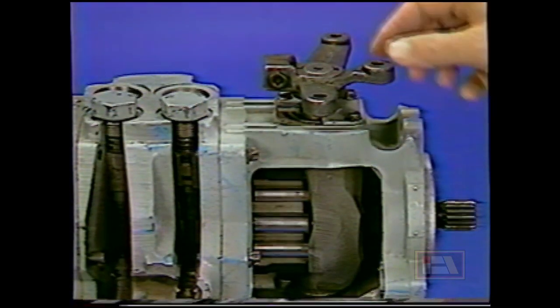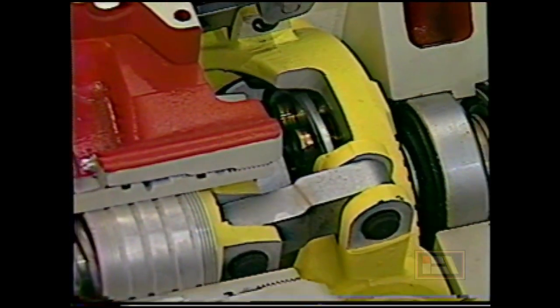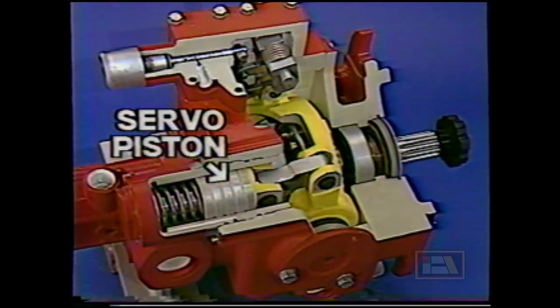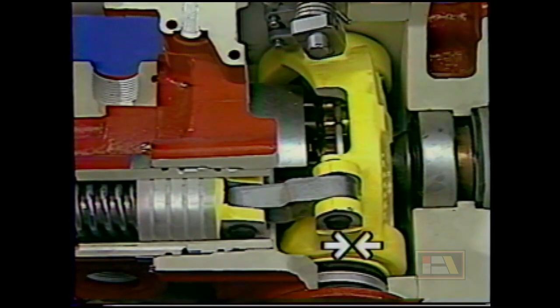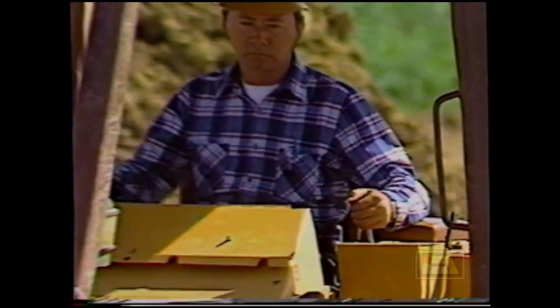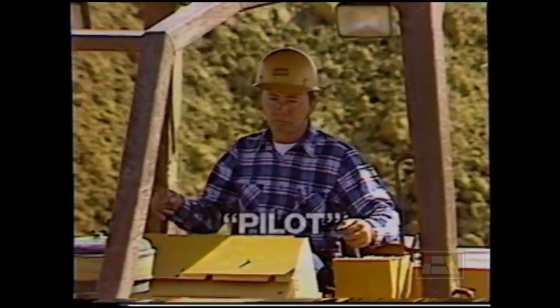Very early methods usually included a simple operator control connected through a linkage to the swash plate itself. The more the operator moved the control, the more angle he would create on the swash plate. In order to achieve more precise control and easier lever movement, the use of servo pistons to operate the swash plate angle was developed. The function of the servo pistons is to simply push the swash plate in and out of stroke. Now, with very little effort, an operator can use a pilot-operated control to move his machine. Here's what is meant by pilot operation.